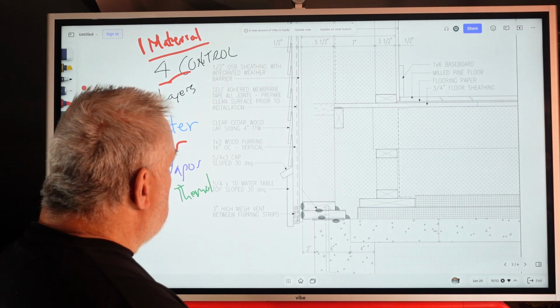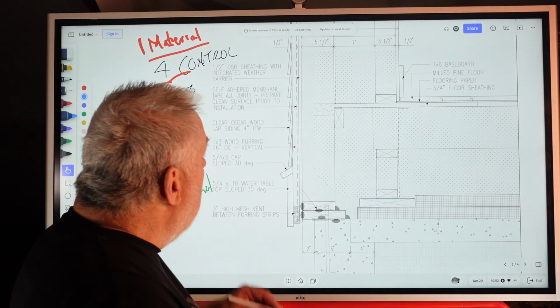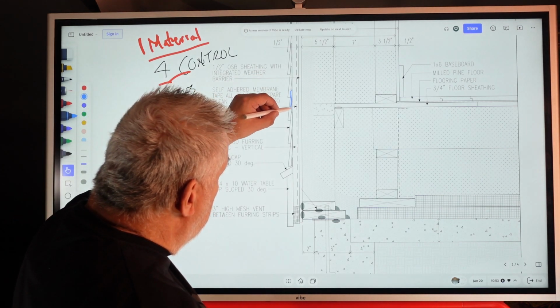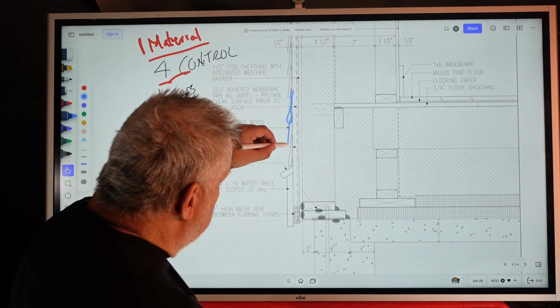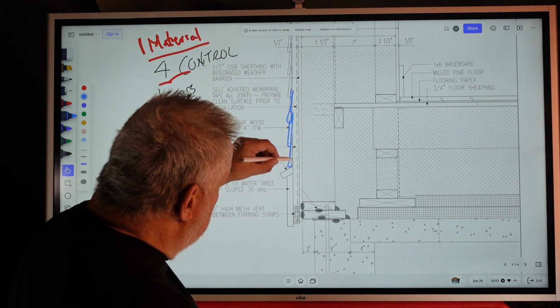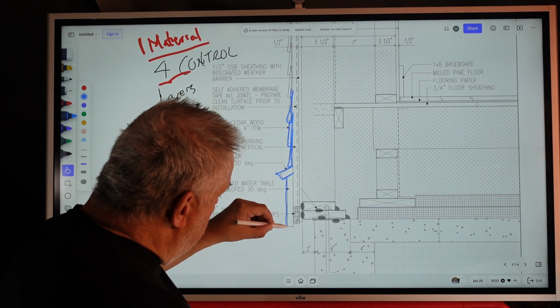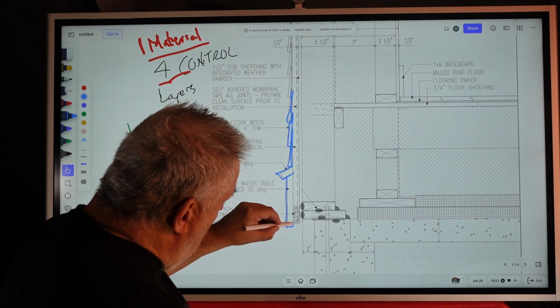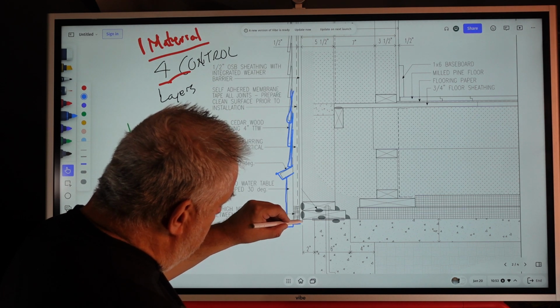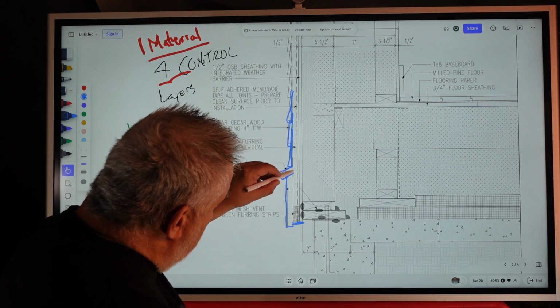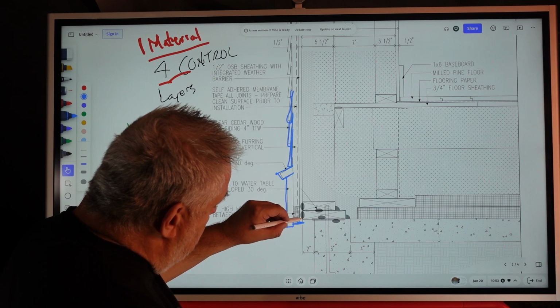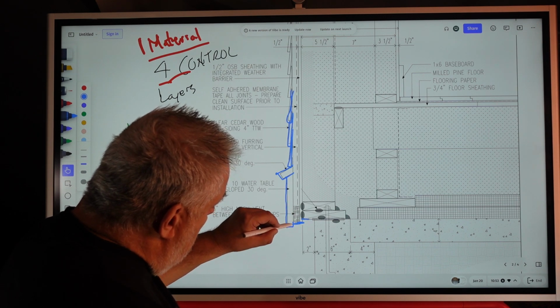So, how did we solve for water here? Obviously, we put a cladding on, right? You can see there's our wood clapboard there. Notice we have a drip cap on top of our water table. Notice our water table, and these are small little details, right? We have our sheathing hangs down below that joint, and then our water table hangs down.